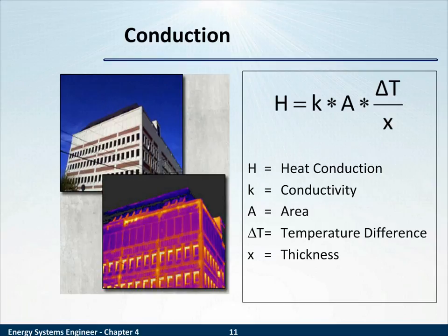But not all of these terms are of equal weight. Take, for example, the thermal conductivity. The property of the material is going to be important as we consider conductive heat loss. The temperature difference is going to be a major consideration as we consider whether the radiative heat transfer or conductive heat transfer predominates. And the next consideration is the thickness. If a component is twice as thick, everything else being equal, the heat conduction will be half.